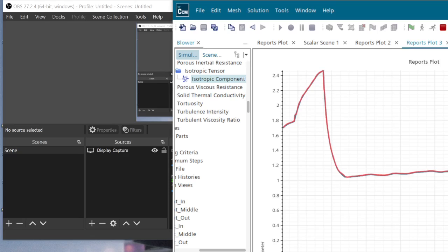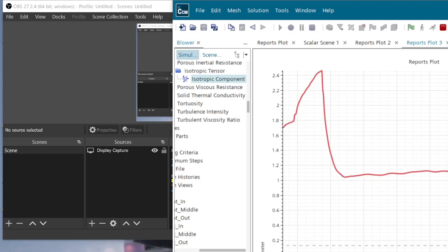bit of air. Let's see if it's resolved any. It's still moving about 1/3 of a cubic meter per second, or that was 100. Let me crank it up to 1,000 and see what it does. But anyways, check for multiple values of I, see what the delta P is, see what the volumetric flow rate is, and try and develop something that looks like a fan curve. It does rather look like that for a value of I of 1,000, it's like 1/8 of a cubic meter per second-ish.